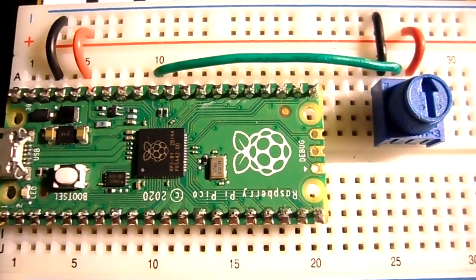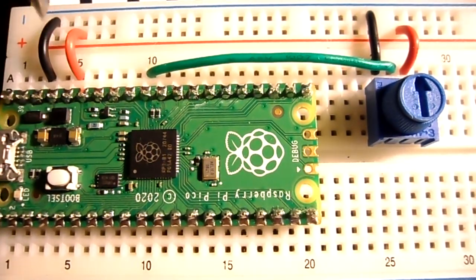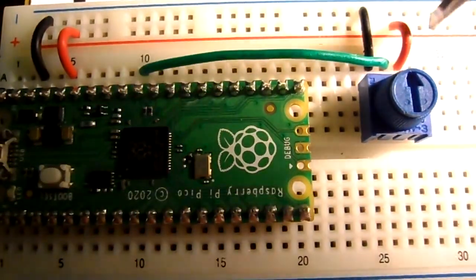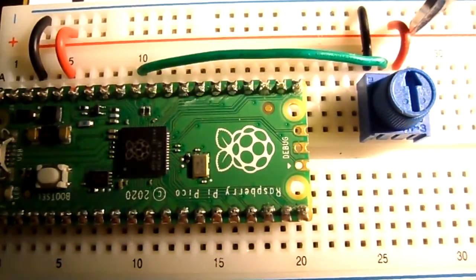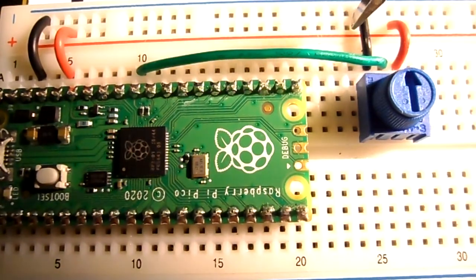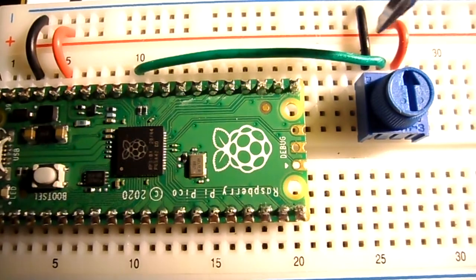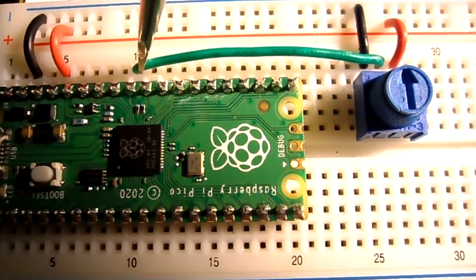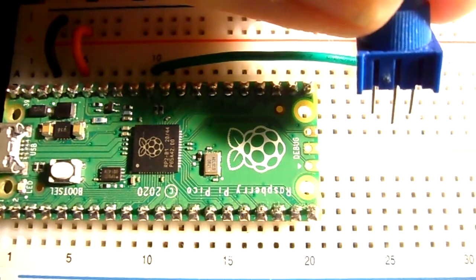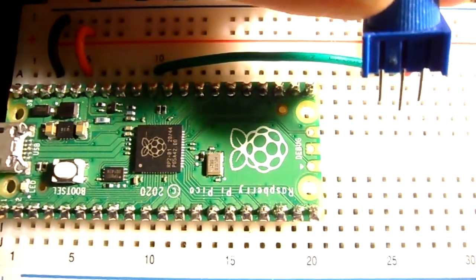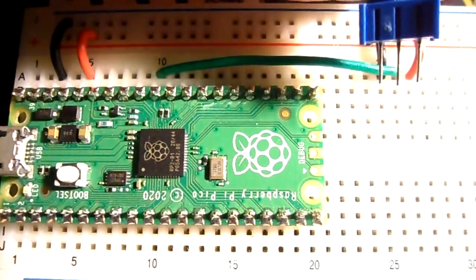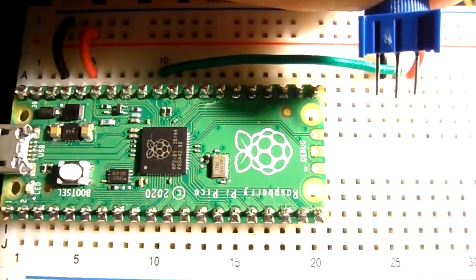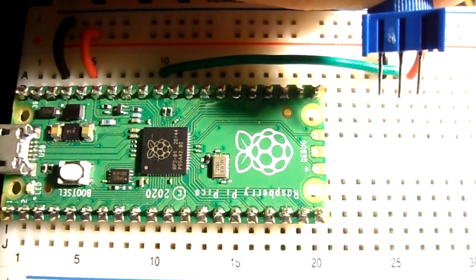So this is my circuit wired up. You can see I have the ground bus hooked up. I have my 3.3 volt power bus hooked up. Down here on my potentiometer, you can see I have power going to this end of my potentiometer, and I have ground going to the other end of my potentiometer, and out of the center, that's where the wiper goes, that goes to pin 31 on my Pico. So I just wanted to give you a close-up of the 3 pins on my potentiometer. And you'll notice the center pin is going to go to the green wire, and the pin on the right of the screen goes to the red wire, and the pin on the left of the screen goes to the black wire.